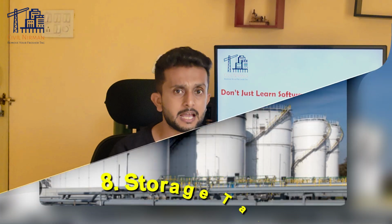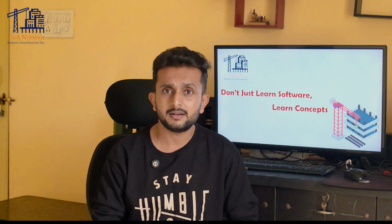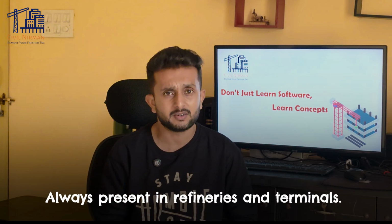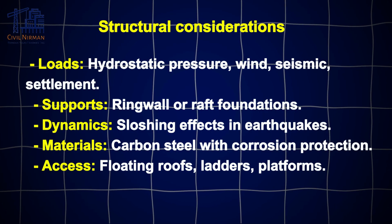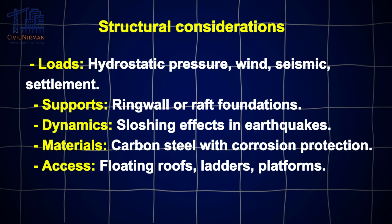On number 8, we have storage tanks. Basically, they are large above ground cylindrical tanks for crude, refined products or chemicals. They are always present in refineries and terminals for storage purposes. In their structural consideration, we have to take care of all categories of loads: hydrostatic pressure, wind, seismic, and the settlement criteria as well.